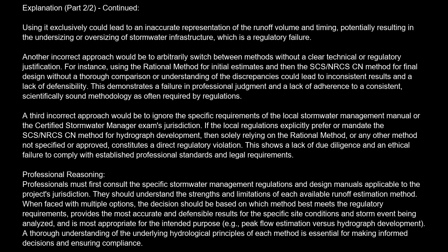Professional reasoning. Professionals must first consult the specific stormwater management regulations and design manuals applicable to the project's jurisdiction. They should understand the strengths and limitations of each available runoff estimation method. When faced with multiple options, the decision should be based on which method best meets the regulatory requirements, provides the most accurate and defensible results for the specific site conditions and storm event being analyzed, and is most appropriate for the intended purpose, e.g., peak flow estimation versus hydrograph development. A thorough understanding of the underlying hydrological principles of each method is essential for making informed decisions and ensuring compliance.